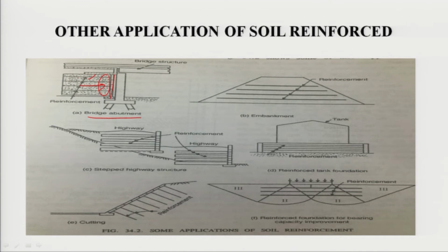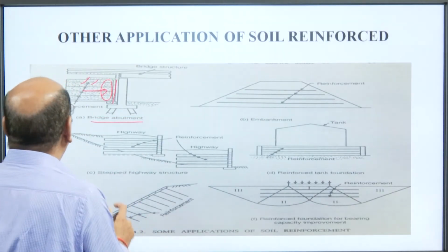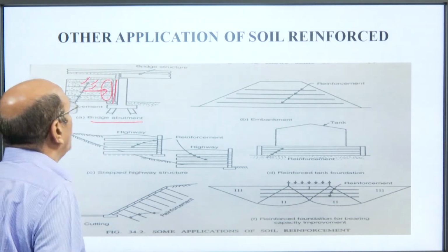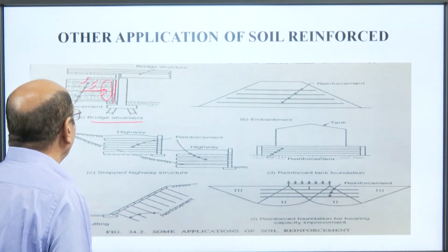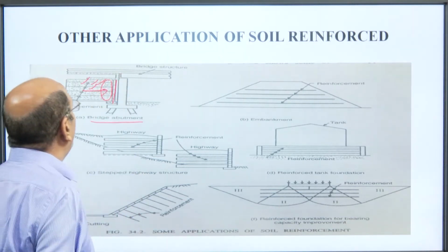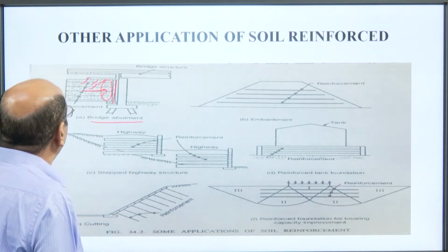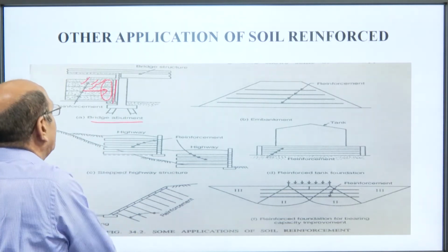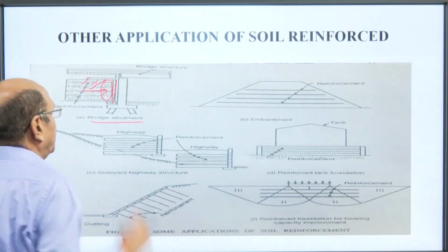After using this reinforcing element, the stresses developed in the soil mass which cause deformation will be borne by the reinforcing elements and transferred to another place. Due to the use of this reinforcing bar, the stresses developed in this area have been transferred, and so there is no deformation at the abutment point.